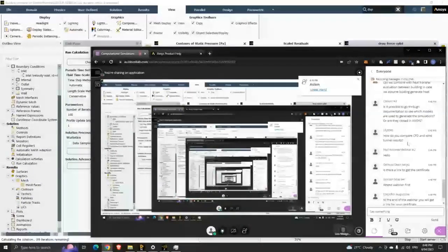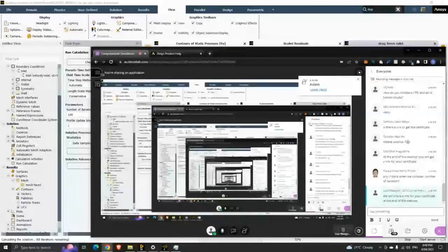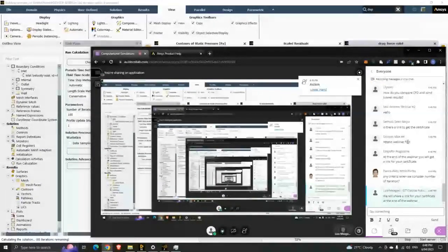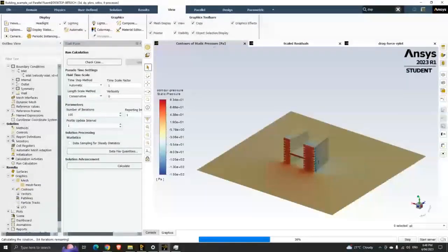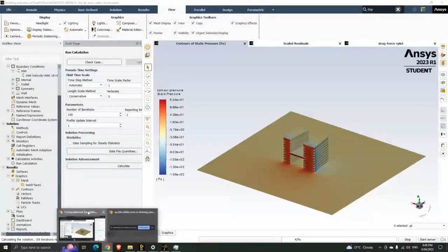There are companies who do wind tunnel tests and also CFD analysis, and they do these internal benchmarks. Suppose you're doing a wind tunnel test: you could create measurements of pressure at different locations on this building, then take the same locations in CFD, get an area average pressure there, and compare the two. You can do things like that.